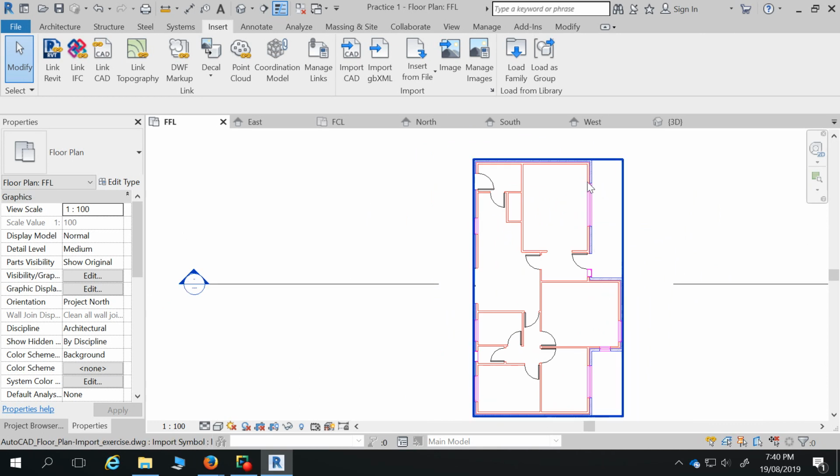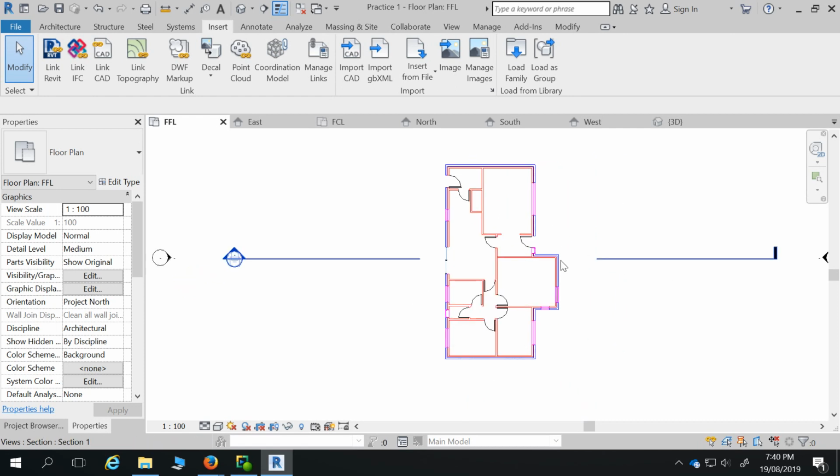We don't want to leave a gap for the windows, because from last week, when we put doors and things in, above the door and the windows is a wall. The window only puts that opening in. If we stop drawing at the window and continue drawing, we won't be able to host a window and door, because essentially there's got to be no wall there. So we want one piece around each side.